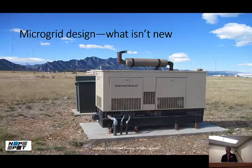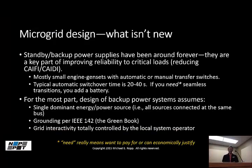Now, a lot of things about microgrid design are not new. You all recognize this as a Generac diesel. This particular one is at the National Renewable Energy Laboratory's test facility outside of Boulder. But we've had standby and backup power supplies forever. Most of these are small engine gensets, maybe natural gas powered, so that you're actually working with two grids. The power grid fails, the gas grid hopefully is still there. It gives you a little bit more reliability, but most of them have a transfer switch. It may be automatic, but it's not seamless. So you'll transfer from the grid to off grid with maybe a 30, 40 second blackout.